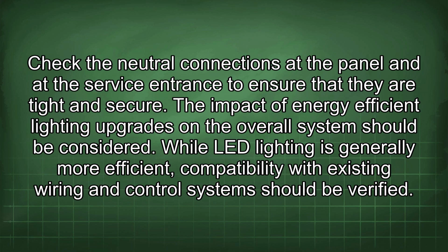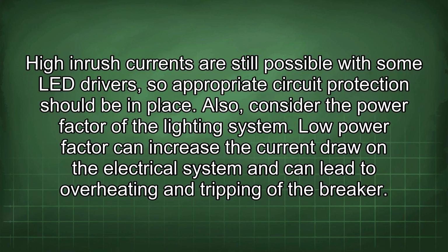The impact of energy-efficient lighting upgrades on the overall system should be considered. While LED lighting is generally more efficient, compatibility with existing wiring and control systems should be verified. High inrush currents are still possible with some LED drivers, so appropriate circuit protection should be in place.